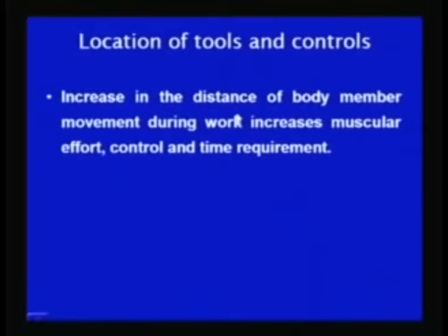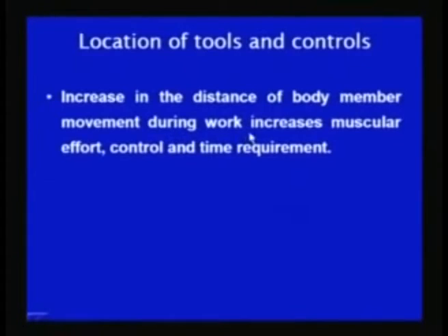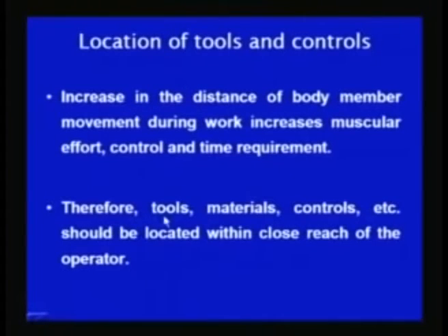So, increase in distance of body member movement during the work increases the muscular effort, the control and the time required for carrying out the job, and that is why the tools, materials and controls should be located in such a way that the distance of body member movement during the work is minimum, so that the related muscular effort, control and time required can be reduced, and therefore, tools, materials and controls etc. should be located within close reach of the operator.